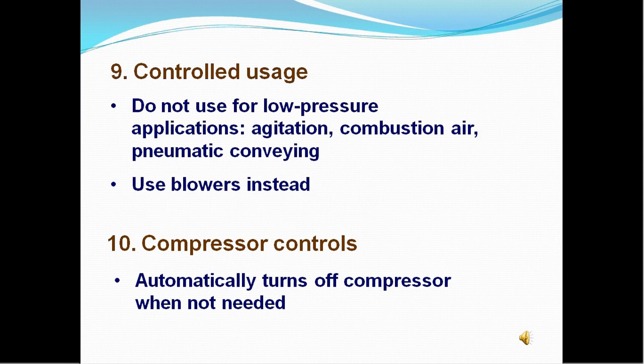Controlled usage. Since the compressed air system is already available, plant engineers may be tempted to use compressed air to provide air for low-pressure applications such as agitation, pneumatic conveying or combustion air. Using a blower that is designed for lower pressure operation will cost only a fraction of compressed air generation energy and cost. In some companies, staff use compressed air to clean their clothes. Apart from the energy wastage, this is a very dangerous practice.